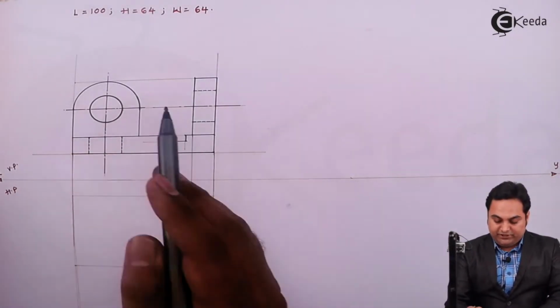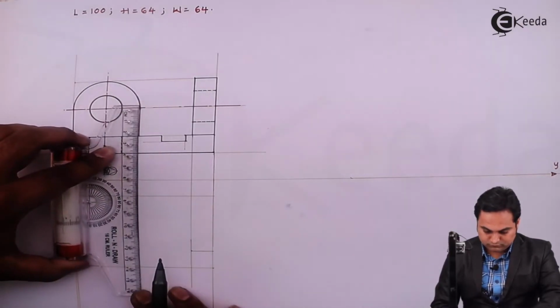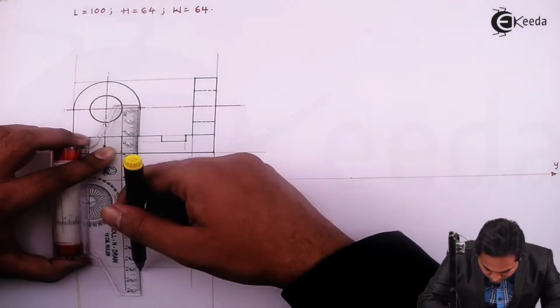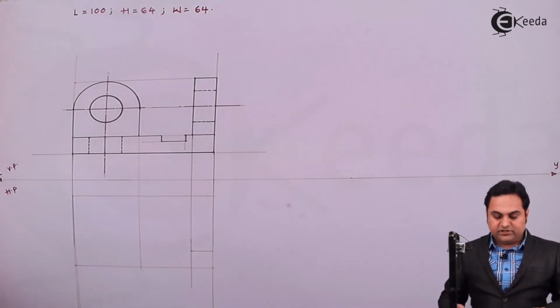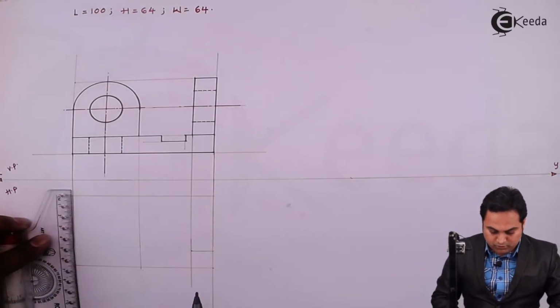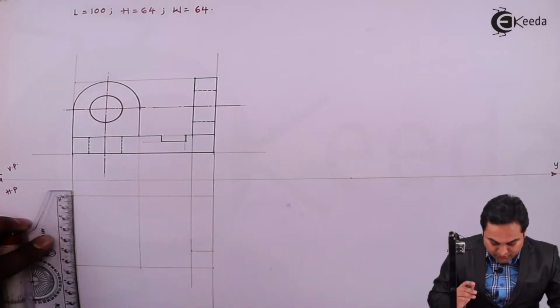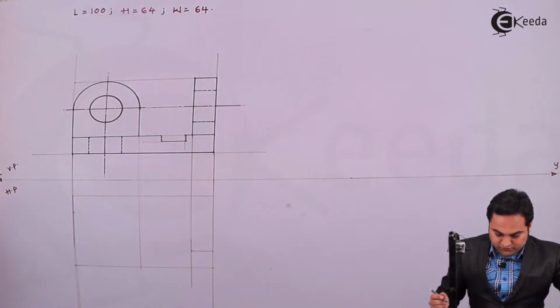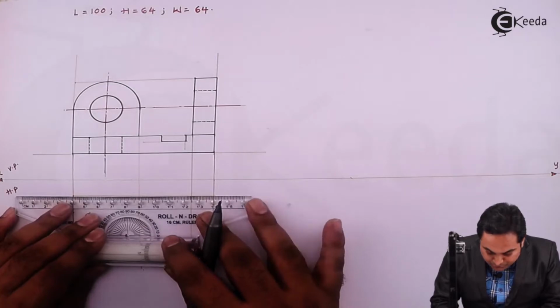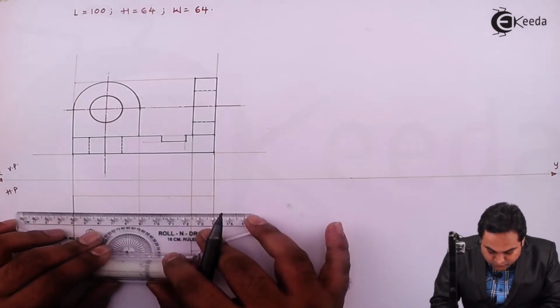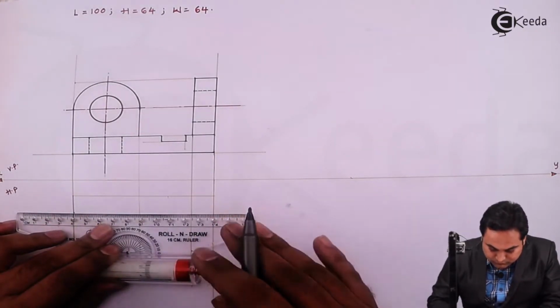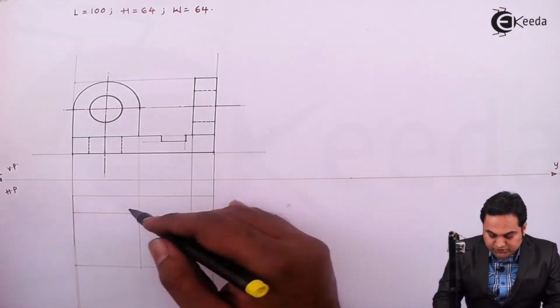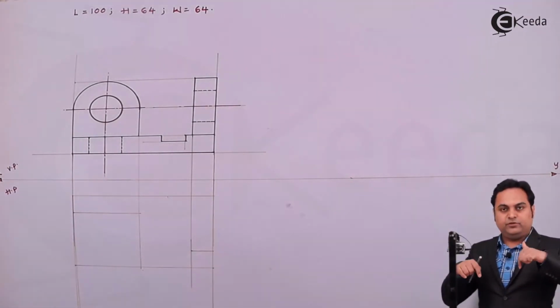This length is 48 and the width is 15 mm. So measuring 15 on one side, which is the width of the semicircular part, taking it downwards. So these two semicircles will be visible from the top.